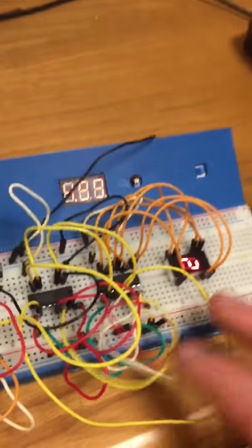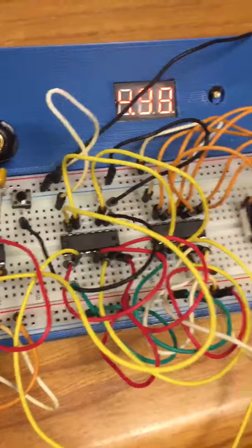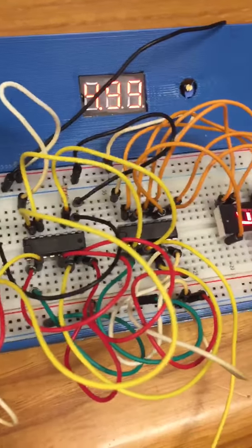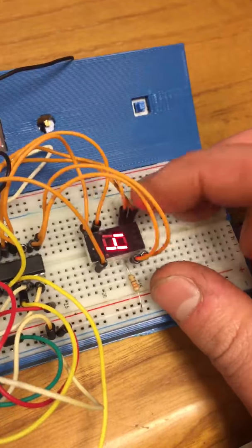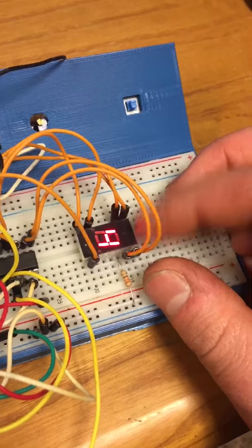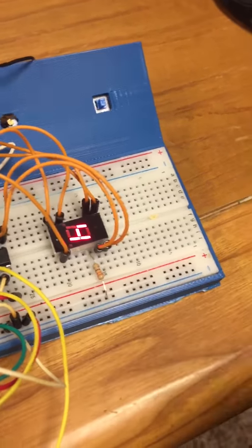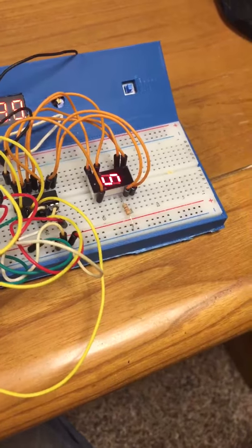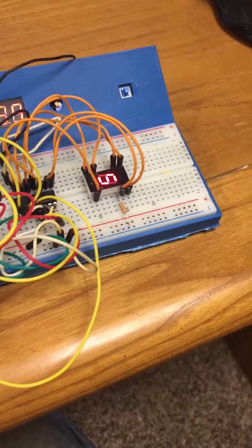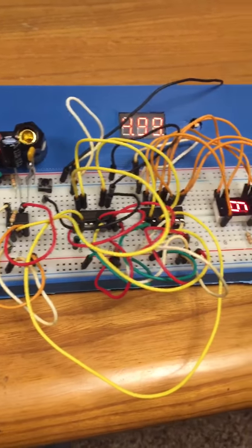So in conclusion for this lab, the thing that was most important for me to realize is the orientation of things. With the chips, it's pretty easy to tell with the little notch at the top, whereas with the display, I had an issue where I kept hooking up the inputs incorrectly. Originally I had A and B over here, where A and B should have been here, and it was a mess, so it kept giving me weird output. I was able to recognize the issue pretty easily, but correcting it took me a while. Other than that, everything pretty much worked on the first try.